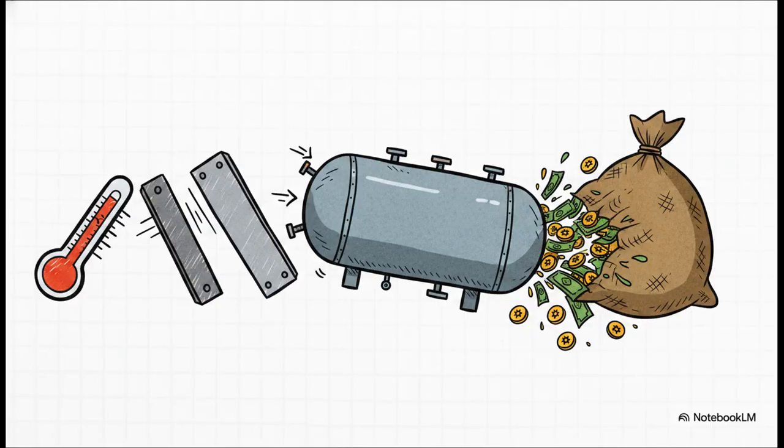So, the absolutely crucial point here is understanding the domino effect of that single degree. That sudden 7% drop in your material's allowed strength means your original design is now legally unsafe. You can't use the same thickness of steel anymore. You have to upgrade to thicker metal plates just to compensate for the weaker state of the hot metal. And thicker plates mean heavier equipment, drastically higher material costs, and massively increased fabrication time. Literally, 1 degree can heavily drive up the financial cost of an entire multi-million-dollar project.